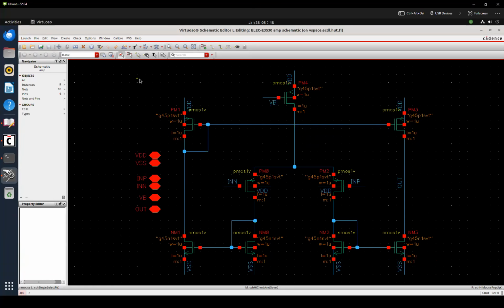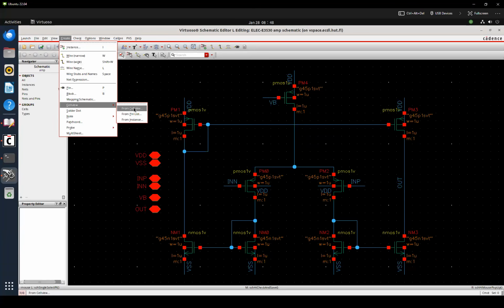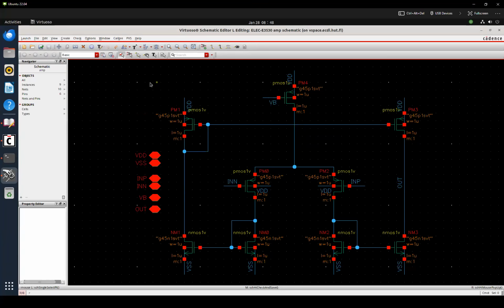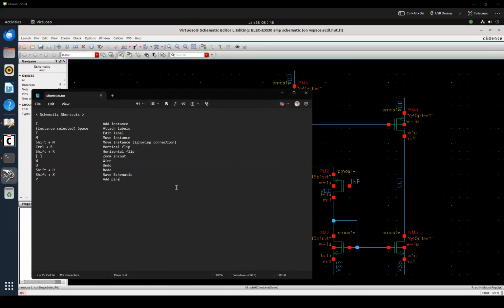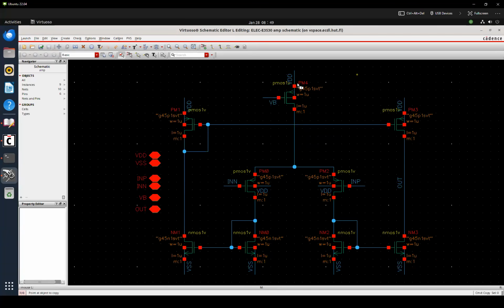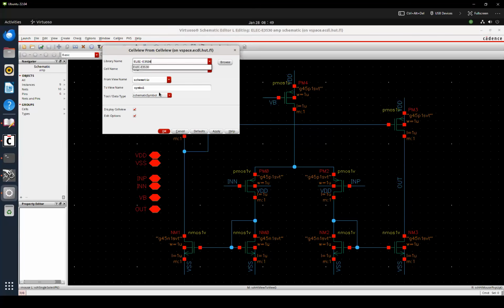And then after that, we can make a symbol, right? For the symbol, what I do is just press Alt C, C, and C. What it means is that we can go to create cell view, and from cell view, but rather than using this way, Alt C, C, C goes to create a symbol. So Alt CCC. What is happening here? Then it goes like this.